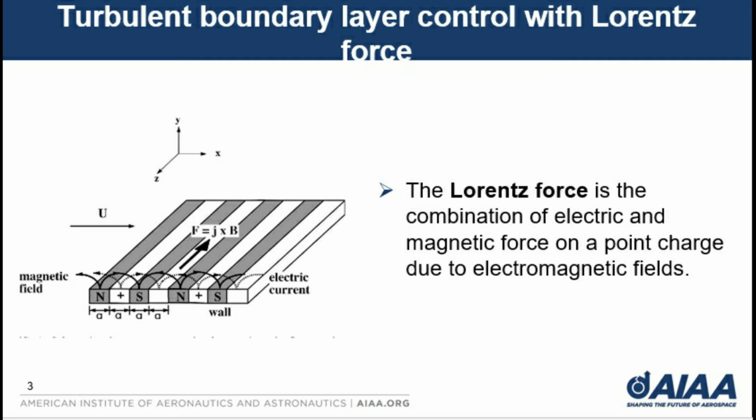This procedure will be centered on drag reduction, by disturbing the semi-equilibrium state between the near-wall streamwise vortices and the wall. This method postulates that the most effective way to achieve the drag reduction is to introduce the Lorentz force perturbations perpendicular to the forces. The required Lorentz force will be created by placing electrodes and magnets side by side, parallel to one another, as shown in the image. The results were applied for different oscillation periods and with a Reynolds number of 100.